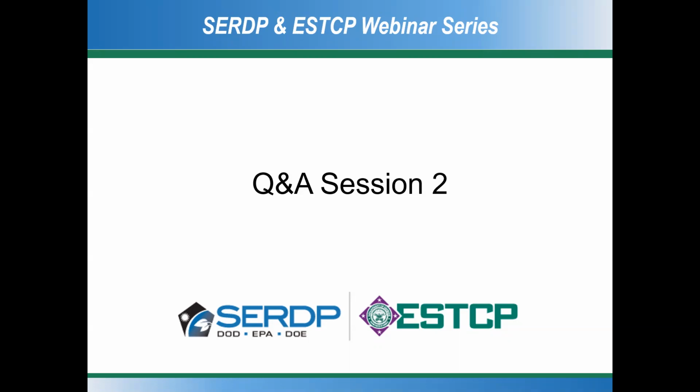Thank you, Joe. And a follow-up question from the same individual at the Army. Can a munition experience multiple liquefaction events? I would say yes. You could have one storm that comes along and buries it, and a second storm that follows behind it. I think even within a given storm, waves in nature and during storms aren't monochromatic the way they might behave in the laboratory. They come in groups, and groups have different amounts of energy. So certainly you can see multiple liquefaction events. And I really hope that this is what we will prove to you with our observations that we're going to be making starting in December.